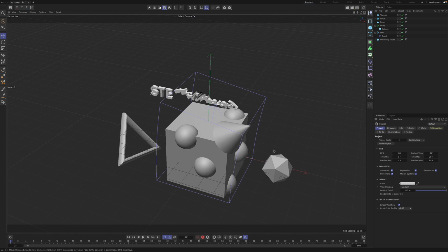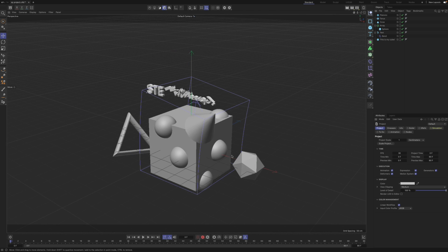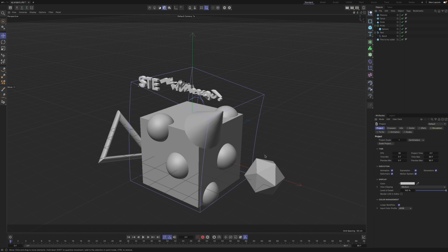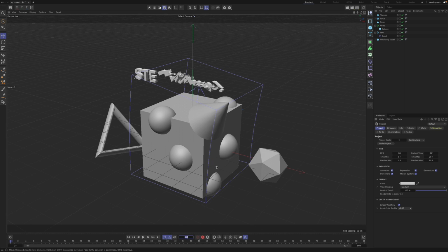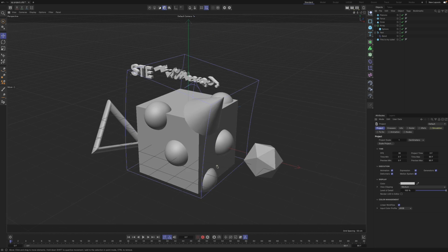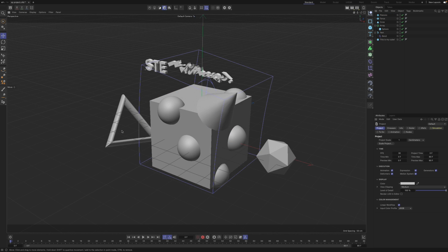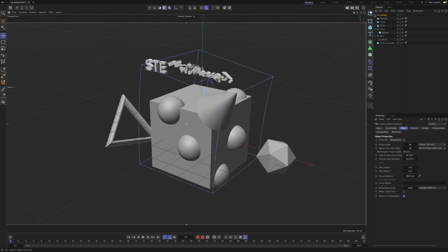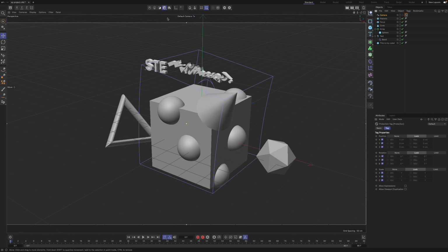So I'm just gonna pan here, do that. I can hold control and zoom in. You can hold tab and scroll up and down, and shift is horizontal. And that looks good to me. I'll hold option to get a little bit more of an angle here. We can actually hit the camera button, camera. We can right click, click on rigging, and then go to protection, and then set like this, and now we view from that perspective.